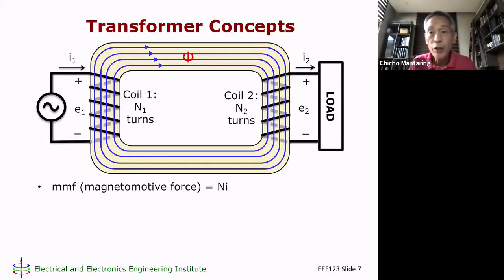This is something that you're going to take up when you take up magnetic circuits. This is actually called a magnetic circuit. In a magnetic circuit, your flux is likened to current, reluctance is likened to resistance. And then the product of current and the number of turns is called your magnetomotive force. In electric circuits, the analog of that would be your electromotive force or voltage.